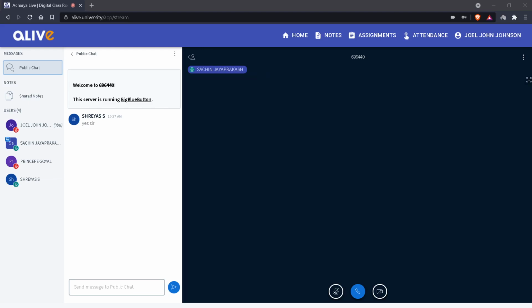Okay, so in the initial phase, we are not waiting till the 3D is done and later going to do the filleting for this part. There is a sketch fillet which we can do in the initial part itself. And similarly, this is chamfer. Again, same product. If you want to do the chamfering, you can do it, and you can confirm it here or on the left hand of the screen.